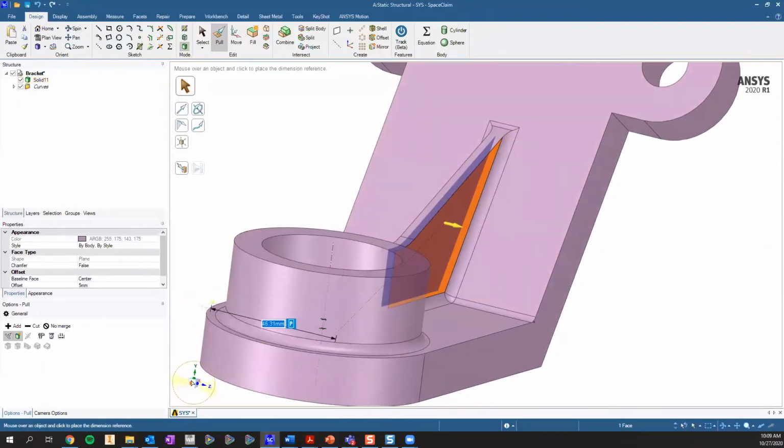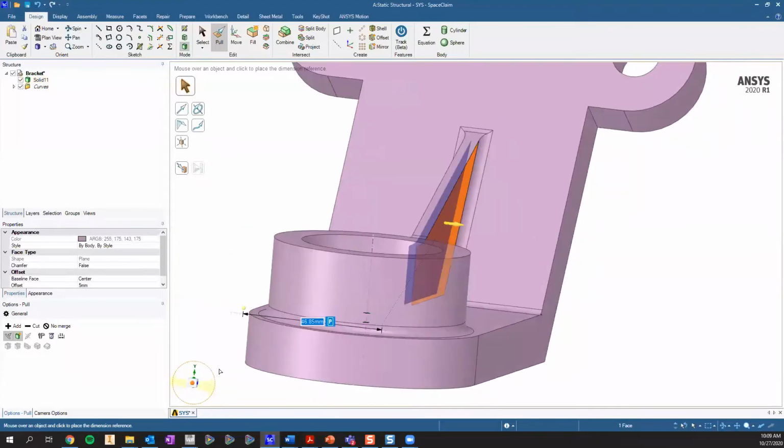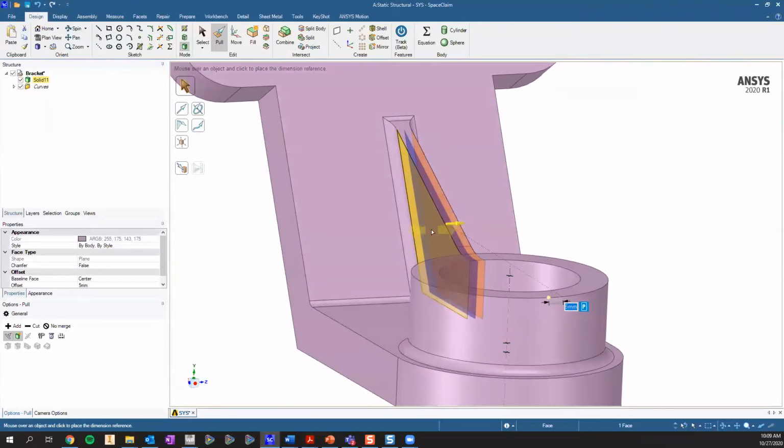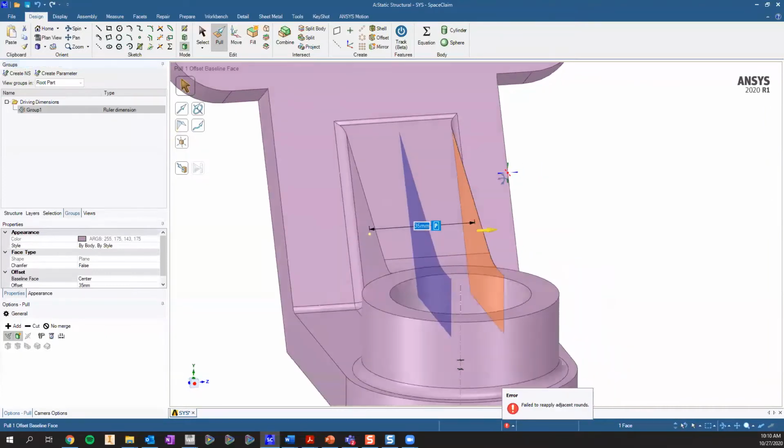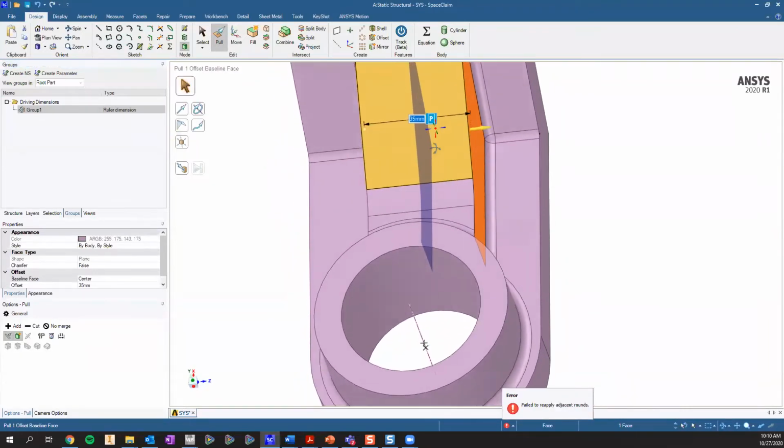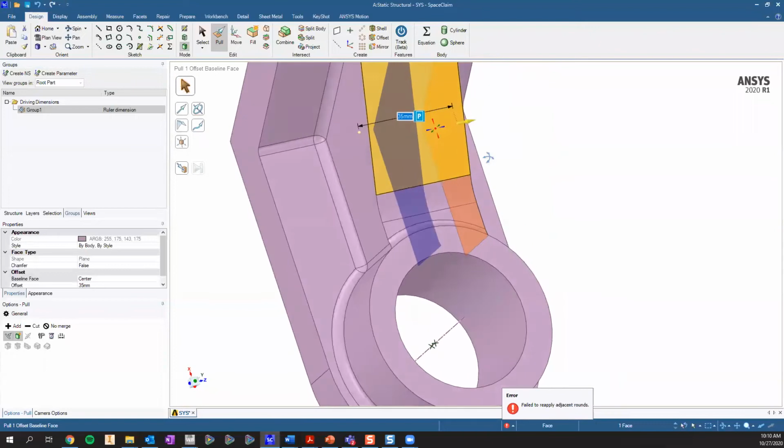And right now it's set to the right face. And I'm going to make that ruler on the left side of this face. And it's currently 5 millimeters thick. And I'm going to parameterize this. So that should give me the ability to offset this. So if I type in 20, it's going to offset it from the middle. And it's been parameterized.